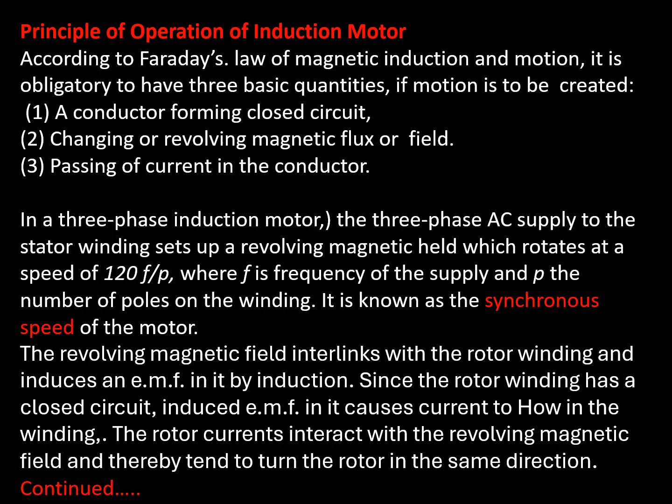Let us know the principle of operation of an induction motor. According to Faraday's law of magnetic induction and motion, it is obligatory to have three basic quantities if motion is to be created. First, a conductor forming a closed circuit. Second, a changing or revolving magnetic flux or field. And third, passing of current in the conductor.